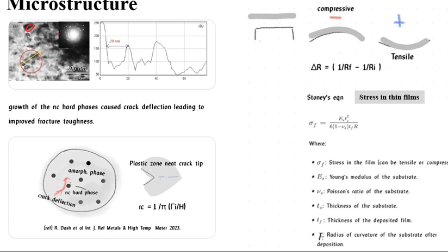Formation of some Kikuchi pattern-like structures also took place, and the SADP pattern showed that there has been some sort of formation of nanocomposite structures. So the dot patterns represent single crystals, while the hollow patterns are near amorphous materials, nanomaterials. So this is actually a combination of different types of crystals that have formed.